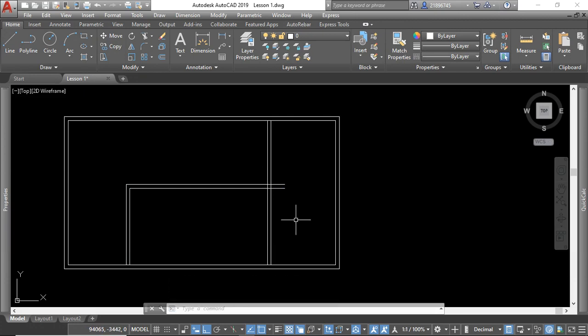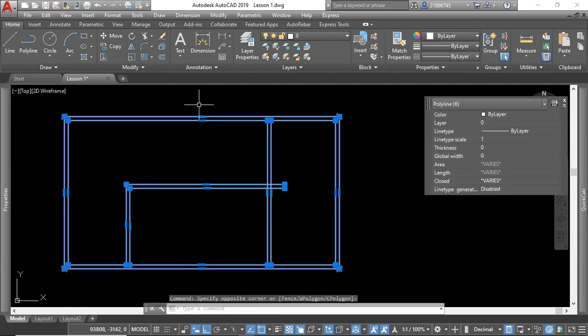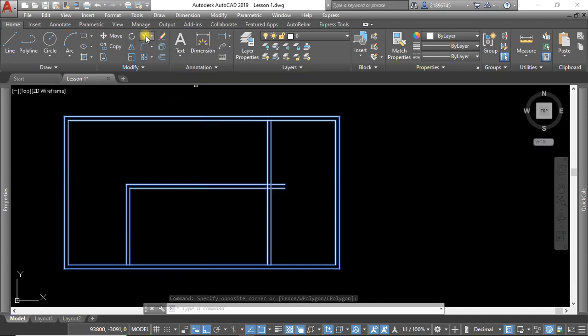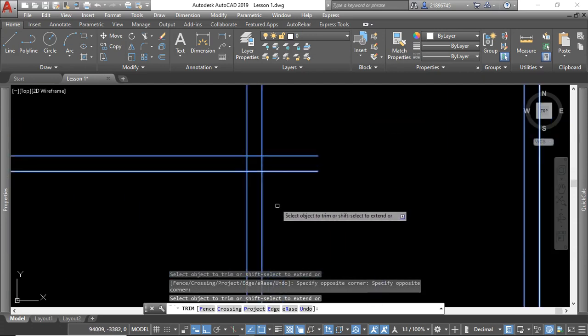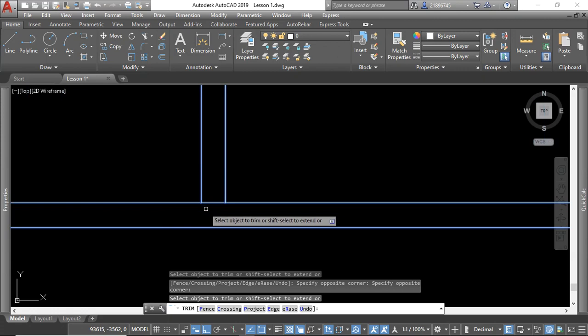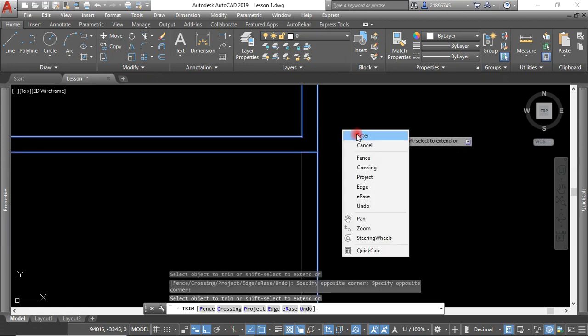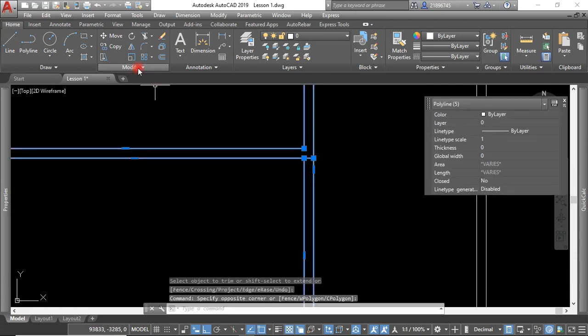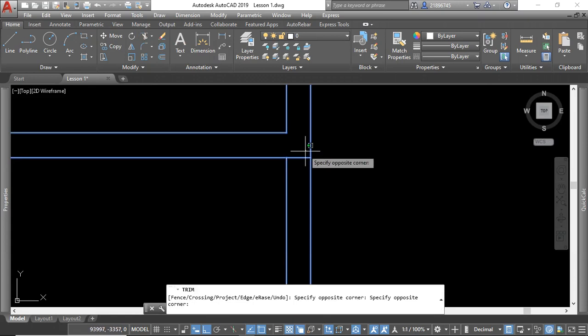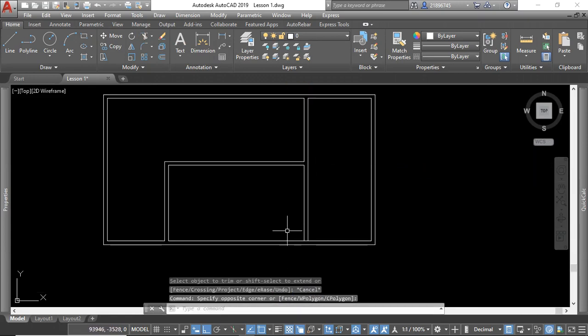So you notice if you input, for example, an offset figure of say 10, the next time you do an offset, it will remember that figure. So that is why if I just press enter, it will just offset you 10. So let's also try something here. We can select all these like that and trim. Okay, so if we trim, we can trim like this. We can also trim like this, and you can also trim here. Okay, enter. So maybe we can select again and trim again like that.